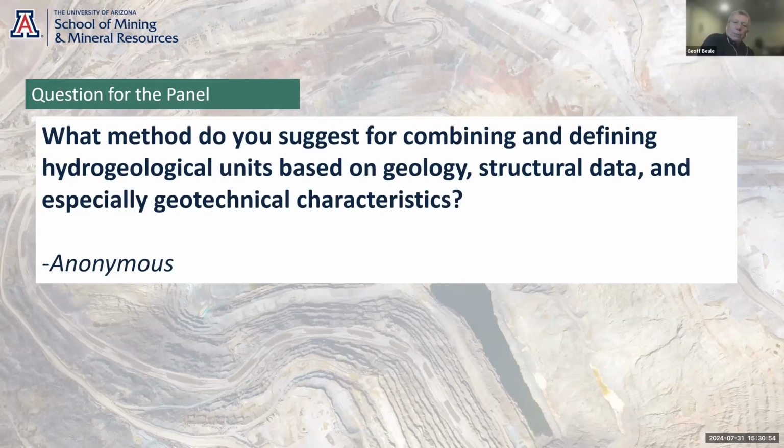Yeah, I think one of the things we say in the course is, for me personally, the first thing I ever do when I walk onto a mine site is look at as much water level data as I can, piezometers and even open standpipes. I look at that way before any permeability data, because if you see water levels between holes which are similar, it's telling you that you've got connection between those two holes.